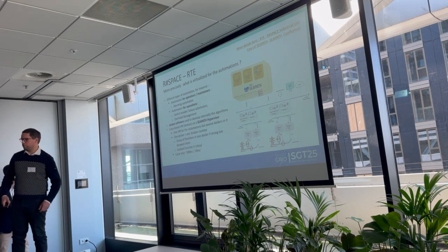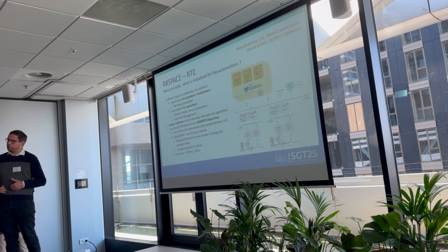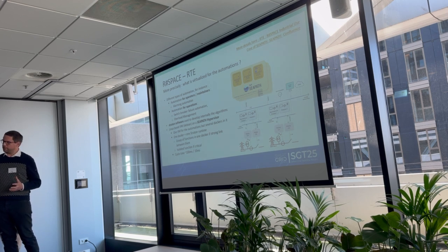That means we have one Linux VM, but we have then several Dockers, and we are grouping the functions. For instance, if we have functions that have strong links between them, we are grouping them in one particular Docker. And if we want to isolate some functions, for instance, the switch breaker failure automation, which is the most critical, I would say, for us, then we can isolate the function in one particular Docker.